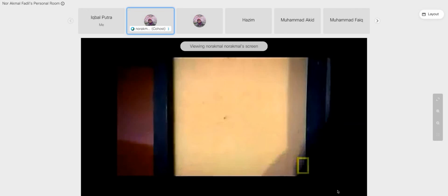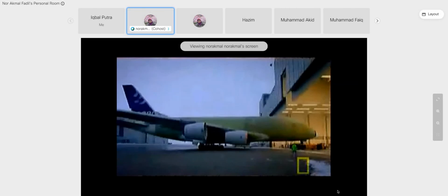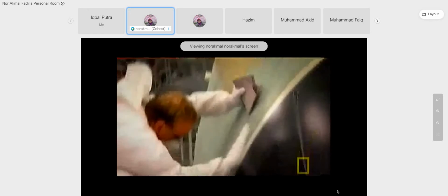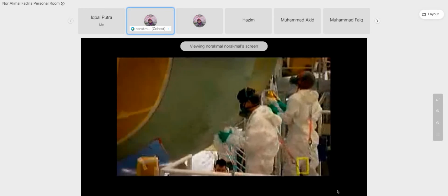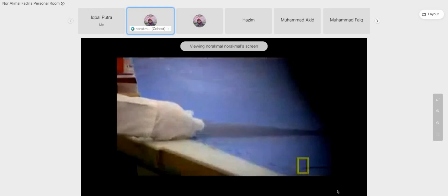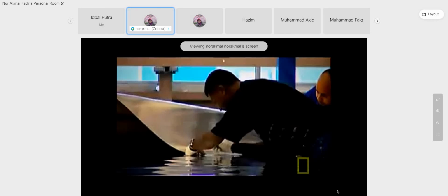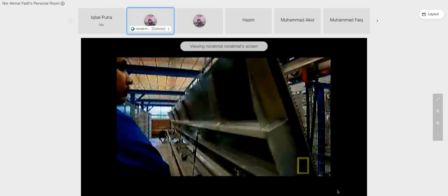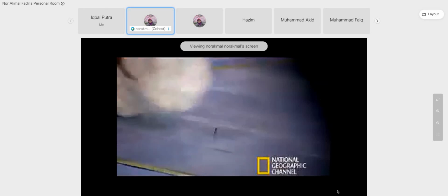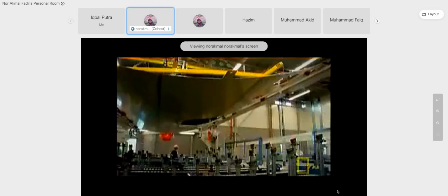Fiberglass is even tougher when combined in a composite with aluminium. It's called glass reinforced aluminium, or GLARE for short. The two materials are sandwiched together in layers. The aluminium provides stiffness, like the buffalo horn in the Mongol bow. Fiberglass is like the sinew in the Mongol bow. It provides the strength that aluminium lacks.